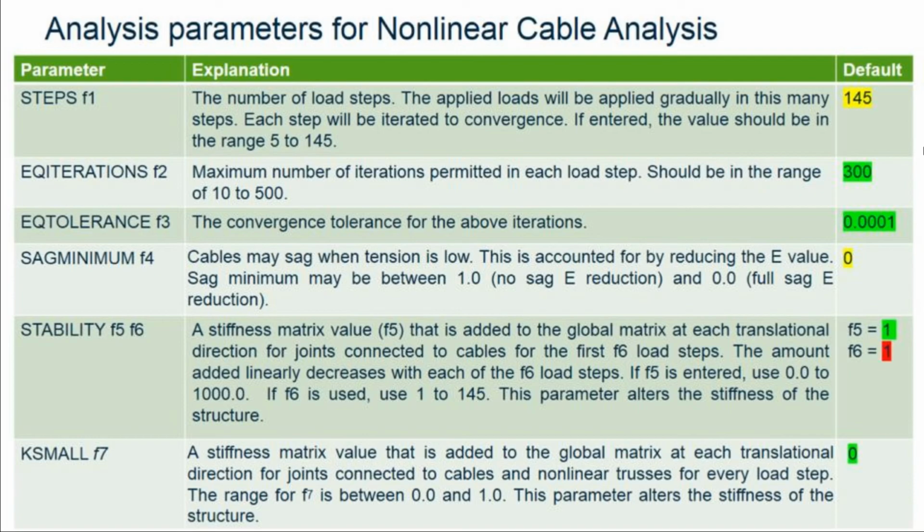For small models, this 145 load steps is good. But when we are analyzing very large structures like cable stayed bridges, which consist of hundreds of thousands or tens of thousands of members, then this will take enormous time for analyzing. So for large structures, you can start playing with this value, reducing it to say 5 or 10.